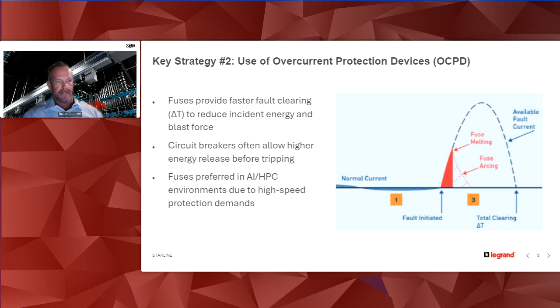So it's widely used, like I said, in more of an industrial environment when you're working with 15 kV, 5 kV switchgear. But we're starting to see it in the data center world now too, with the increase in power densities. So yeah, it's a great way. And in many cases, if you can't get that incident energy down to an acceptable level, well, then the system can't be worked on. So like you said, we're starting to see a little more of that in the data center world with the growing power demand.